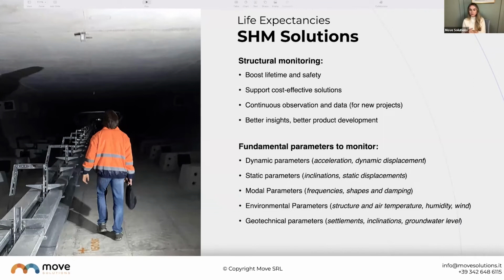The fundamental parameters that we monitor in this case would be the dynamic and static parameters. So the accelerations and the dynamic displacements of the bridge, the static parameters, so the inclinations and the static displacements, and also the modal parameters.